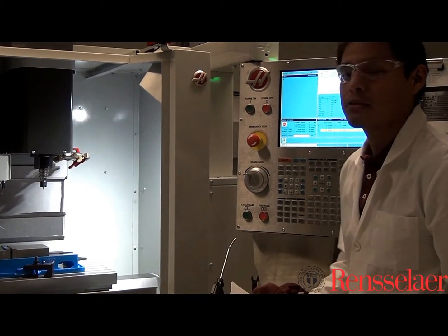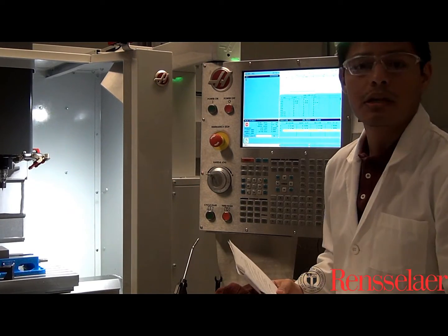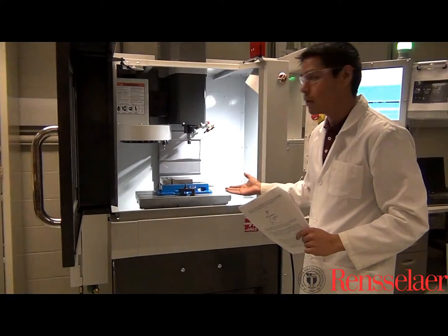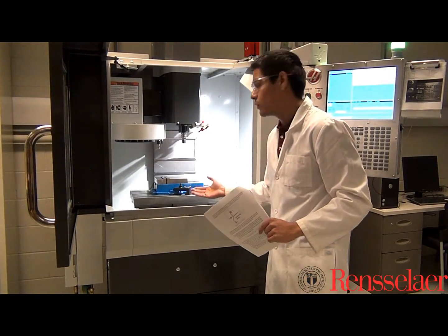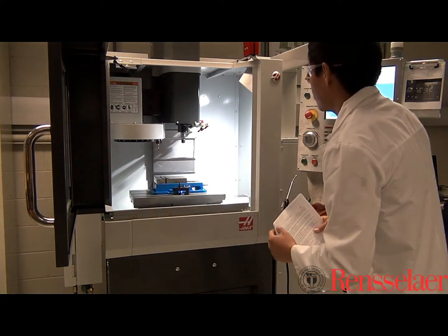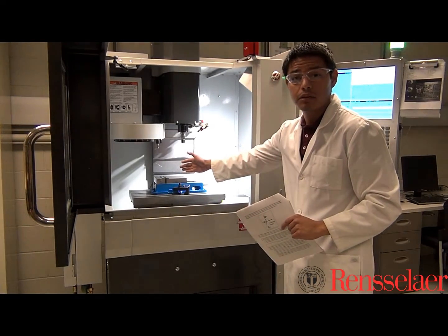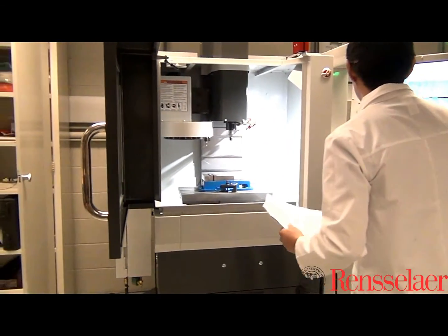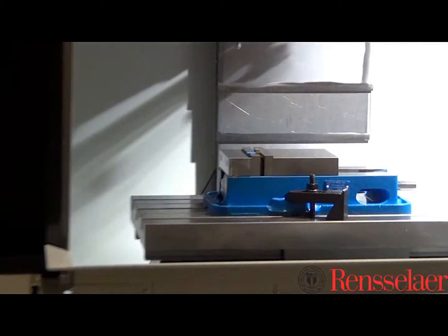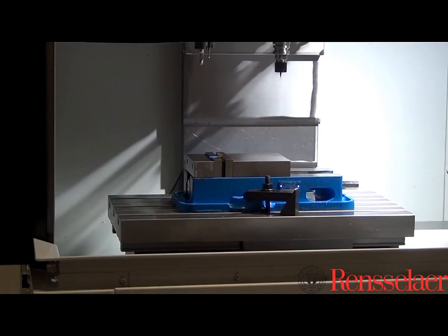Now that we familiarize ourselves with how to control the machine, we're going to start touching off the axes. For the purposes of this project, the way that we produced our code, we wanted to find our axis origins on the bottom left edge. So with that being said, we're going to begin by moving our spindle closer to that edge. And the way we're going to do that, we're going to move in the appropriate axis. So I'm going to start off by moving the spindle closer to the workpiece, like so.